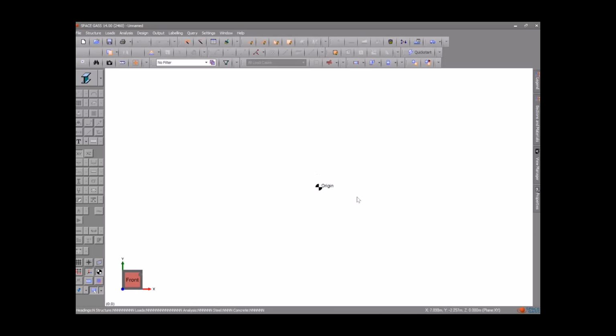We can use the Space Gass software for these examples as well. So in here we can just draw the members. Let's put 0, enter, and we have 2 meters, and from here we can just draw members, touch it here, and we have 2 meters, and we can close it off. This one, escape key.